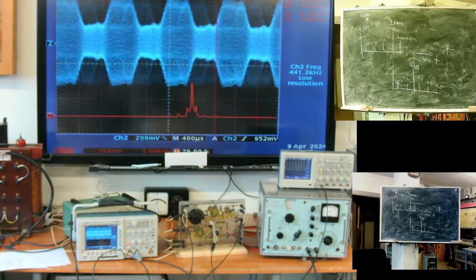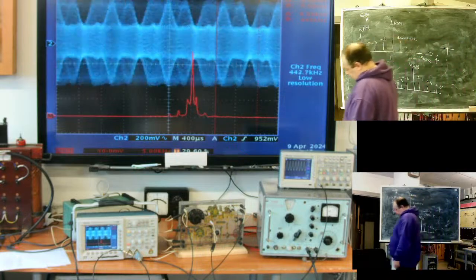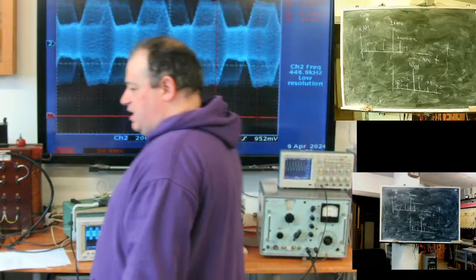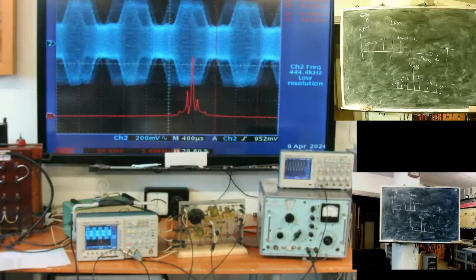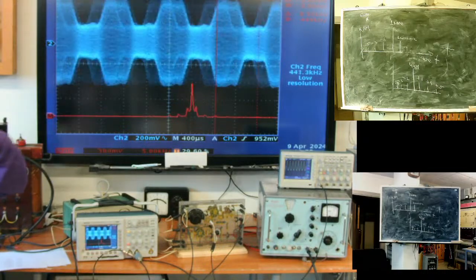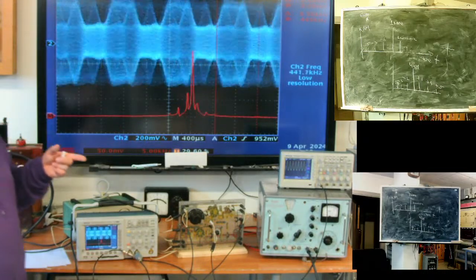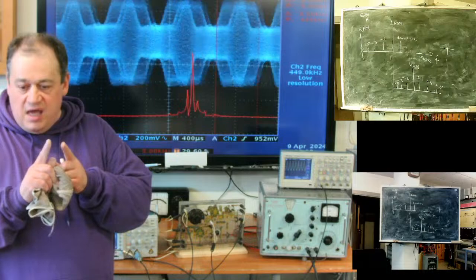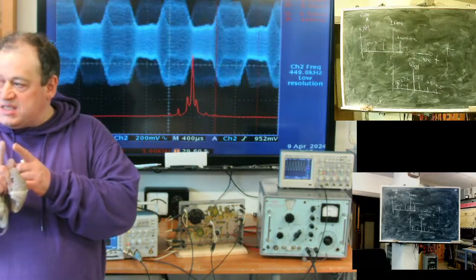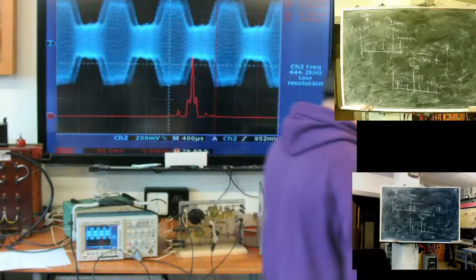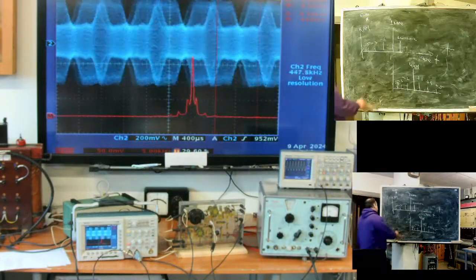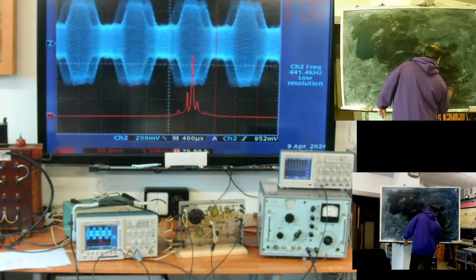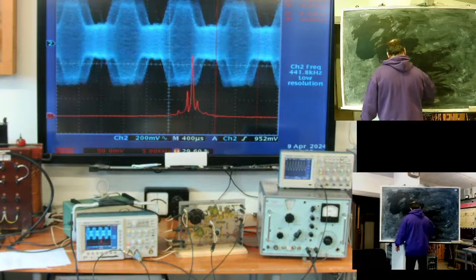See what the problem is? When you need a receiver for only one frequency, it's easy. But when you need a receiver that can be tuned to different frequencies, you will need a bandpass filter with a very narrow characteristic and adjustable. It isn't easy. It's very hard to create such things. So the idea of the so-called superheterodyne receiver dominated the communication market for many, many years.